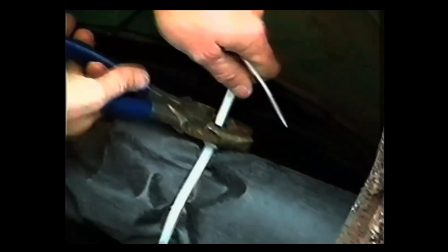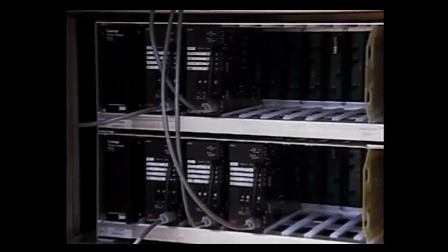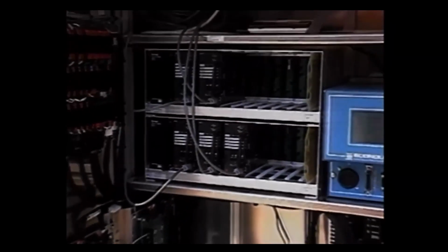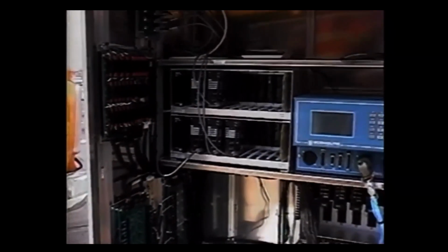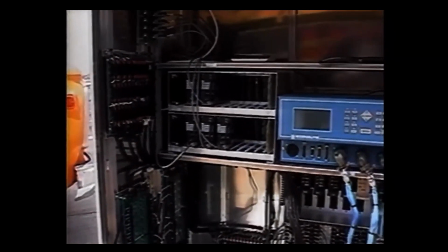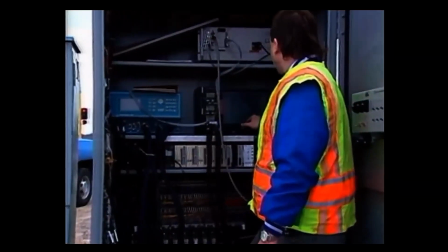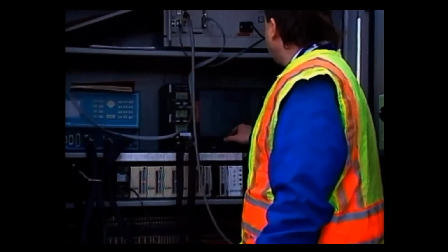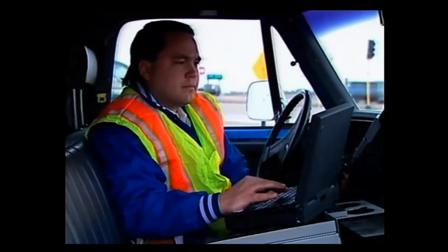Wrapping keeps the conduit free of dirt and debris, yet allows water to move in and out. Route the home run cables to the traffic control cabinet, and then connect them to the 3M Canoga C800 vehicle detector. Then you can verify the installation specification using a laptop computer and program the vehicle detector remotely for optimal